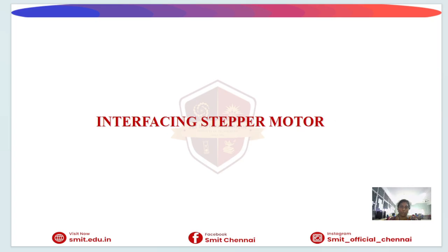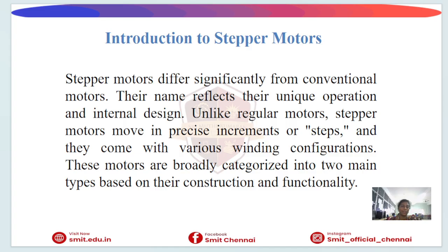Today, we are going to see about stepper motor interfacing, an important topic in embedded systems and automation. A stepper motor is a special type of motor that rotates in fixed angular steps rather than continuously like a normal DC motor. By controlling these steps through the 8051 microcontroller, we achieve precise position control. There are many applications like printers, CNC machines, robotic arms, 3D printers, and camera positioning systems.